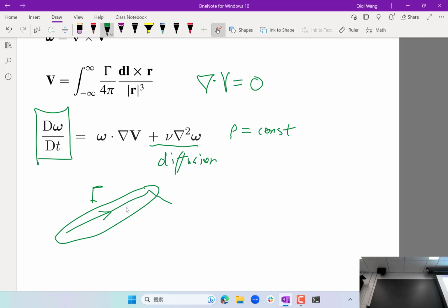If you trace upstream and the point misses the solid body of the wing, then there is no way that location has non-zero vorticity, just because of this equation. That's the most important consequence of the vorticity equation over here. So a place can only have vorticity if, when you trace upstream through the history of that fluid particle, vorticity was generated in its history. And in this scenario, the only reason is that the streamline, when you trace upstream, would touch the surface of the wing.